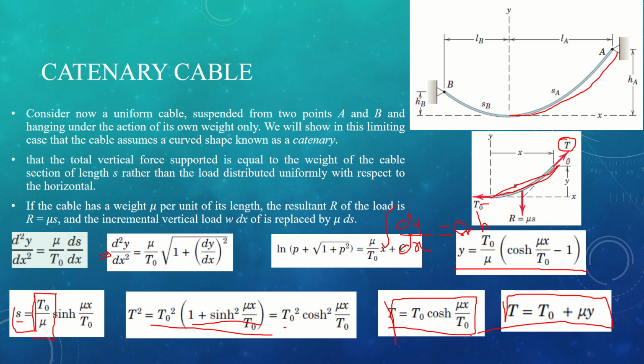Now this is a simple formation of the catenary cable design. These equations may seem complicated, but in reality these are simple derivations. All you will be using is the very basic equation, the fundamental boundary equation, that will be the very first one. The rest are all the relations that you need to know: how the weight is distributed, how the length is found, how different arc angles and positions of the tension across the form are found. You also need to remember that the maximum condition would hold when A and B are at the same height and are across the same length.